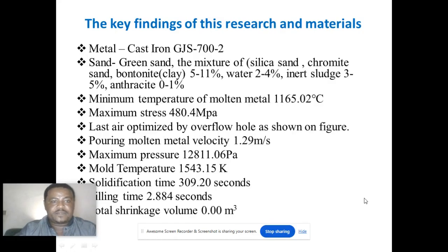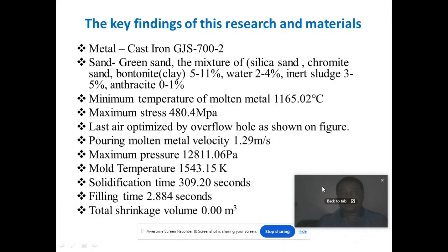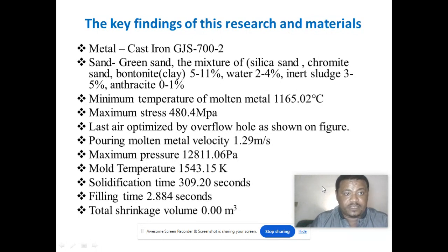The key findings of this research are: the material selected for casting is cast iron; sand is green sand, a mixture of silica and chromite sand, bentonite or clay 5 to 11%, water 2 to 4%, inert sludge 3 to 5%, anthracite 0 to 1%.